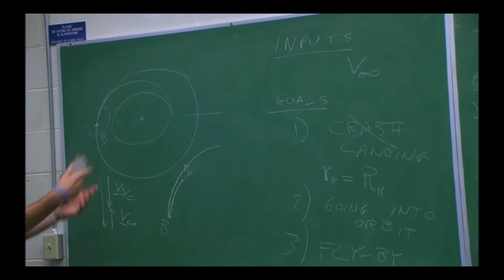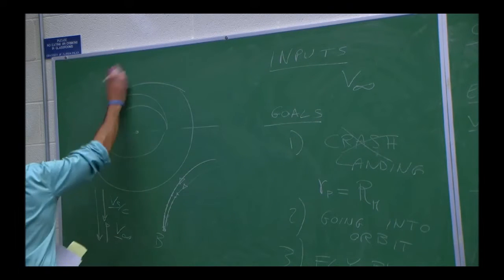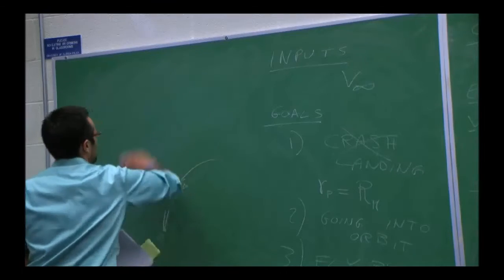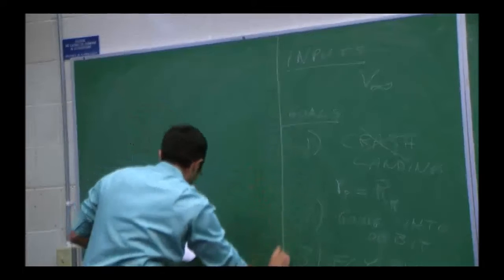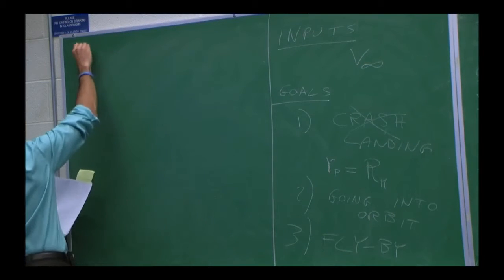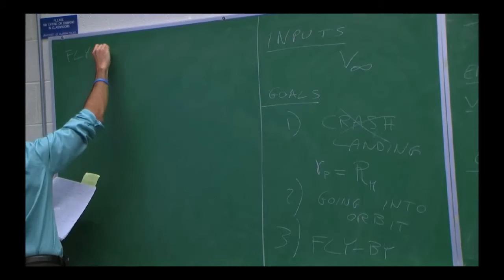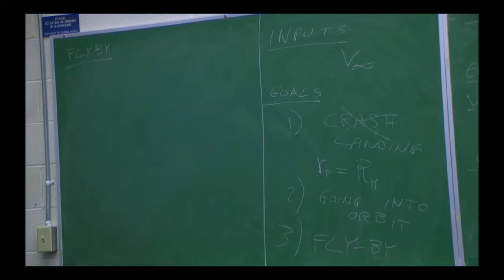But let's figure out a few things here. So how do you solve for the delta? Basically, the delta is all I have to solve for, right? Well, it's the same expressions we saw last time. Nothing new, really. Okay, let's see. If you're doing a flyby, for example, what you want to achieve is a specific turn angle, what is called the turn angle.